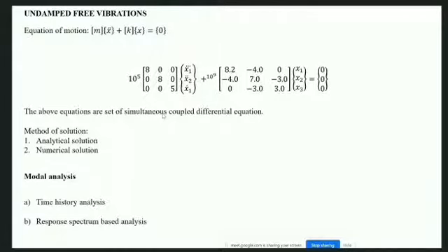the weightage ratio, that means the ratio of participation of various modes in the displacement vector, is changing. Okay, and we have to find out those. First, we have to know the natural frequency and the mode shapes. That will come from structure side.